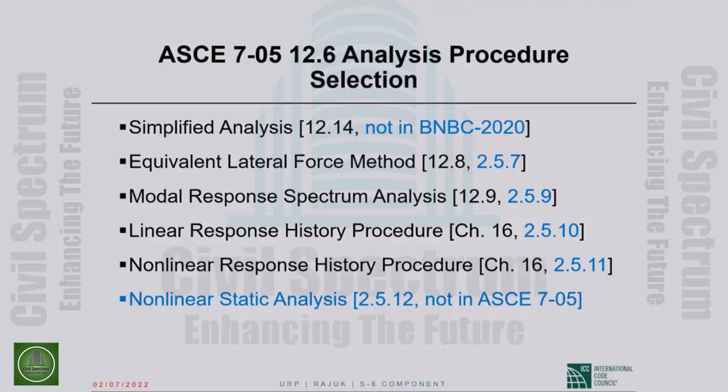And our codes do not have it anymore. In the military document that we put under contract, the nonlinear static has still been maintained, but ASCE 7 does not have nonlinear static analysis.